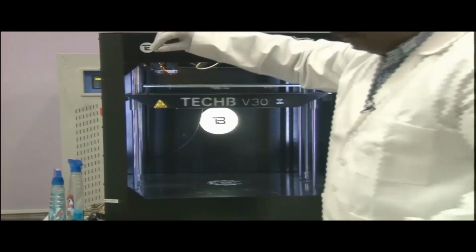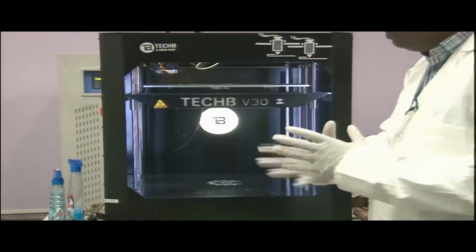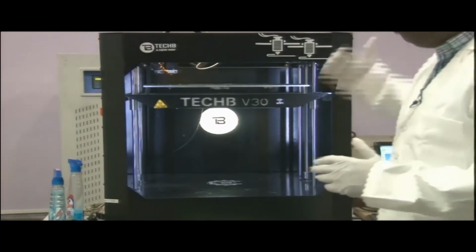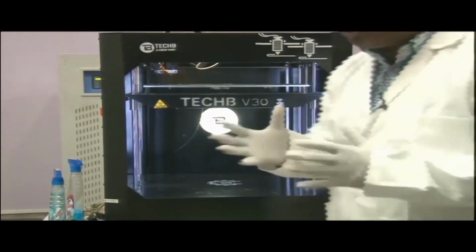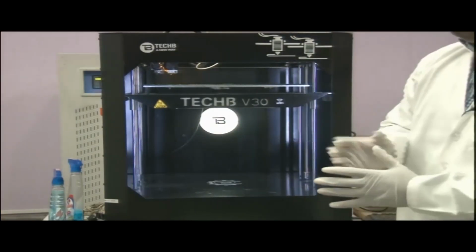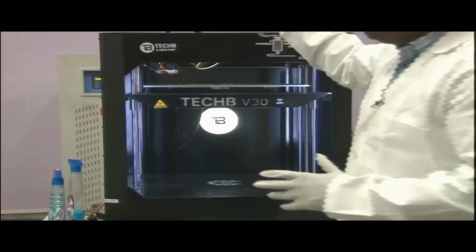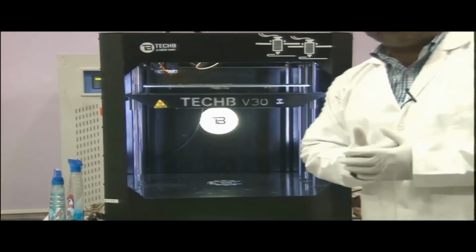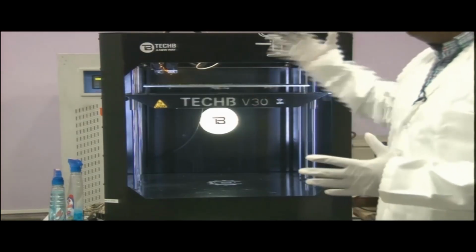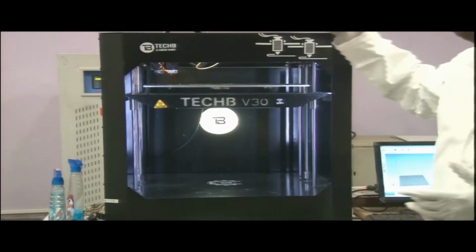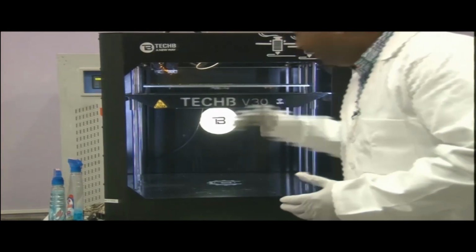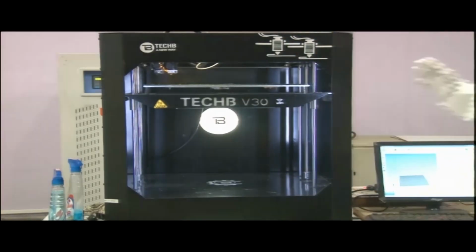Also whenever we start depositing, we have to take care of what we are feeding here. The raw material is in the form of an open spool kept at the back of the machine. When we store this material in boxes, we use silica and calcium, which keeps it moisture free. If our raw material, ABS or PLA as I mentioned, is moist, it obstructs the proper deposition of the job.